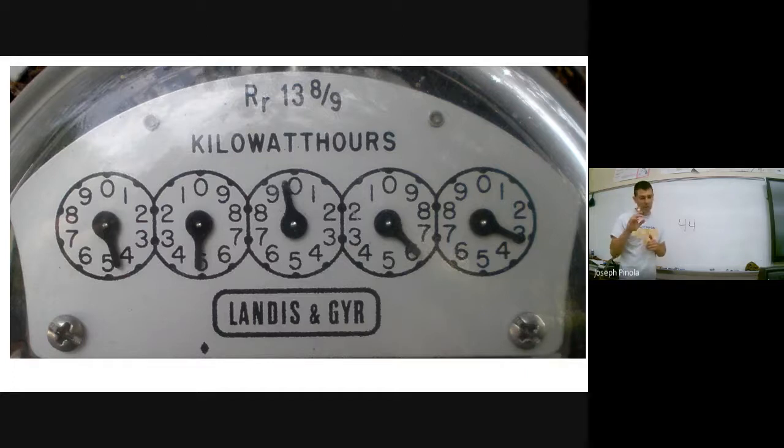Continuing on, the next digit we read from the opposite way again. That digit is not 0, instead it's 9. The penultimate or second to last digit is a 6. That's because, again, we have to flip the direction that we make our measurement from, going 1, 2, 3, 4, 5, 6, and then not quite making it up to 7. And then finally, our last digit, we read the normal way, at least how we would read an analog clock. That digit is slightly past the 3, but not to the 4. So that final digit is 3. This person would have used 44,963 kilowatt hours.